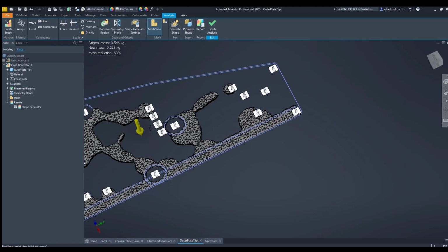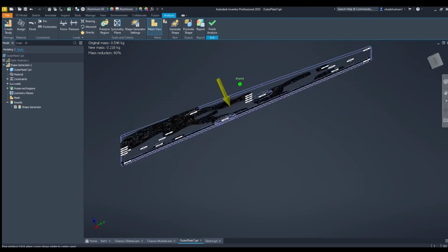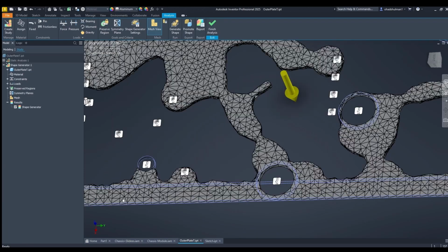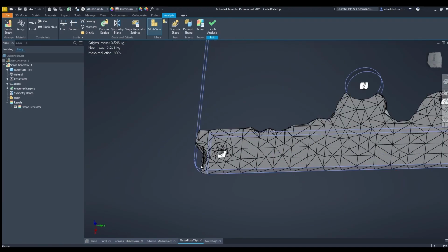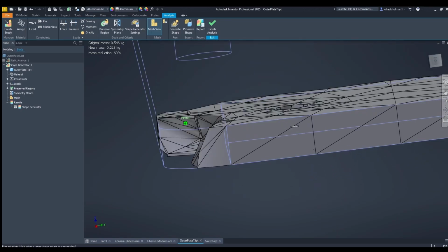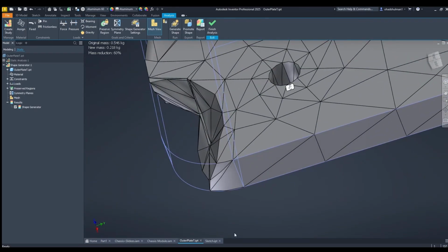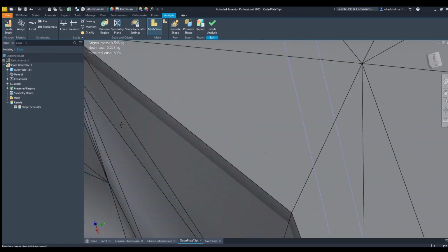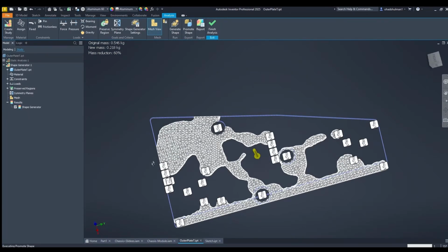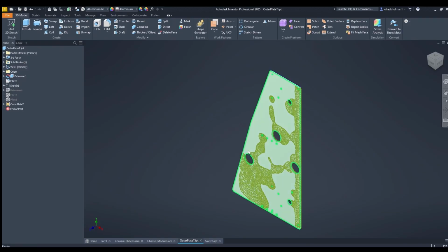Whereas the areas that it emptied out are stronger areas, more resilient, so you can be more aggressive with your pocketing in those areas. So this serves as a nice guideline. You can see here this tiny little place is a place that you can take a little bit off. Again, this is for industrial grade stuff.